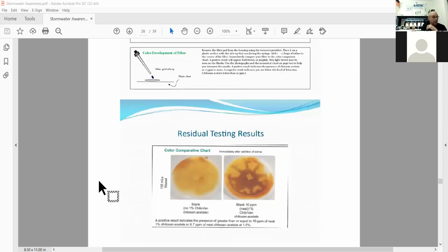And then the testing level is 10% of the maximum allowable threshold concentration. That is determined by taking a population of fish for chitosan. The most sensitive species is rainbow trout. You look at the no effect concentration and the low effect concentration. You take the geometric mean of that, and that's your maximum allowable threshold concentration, reduce that down 10%, and that's what you can discharge at. It's got to meet that or less.